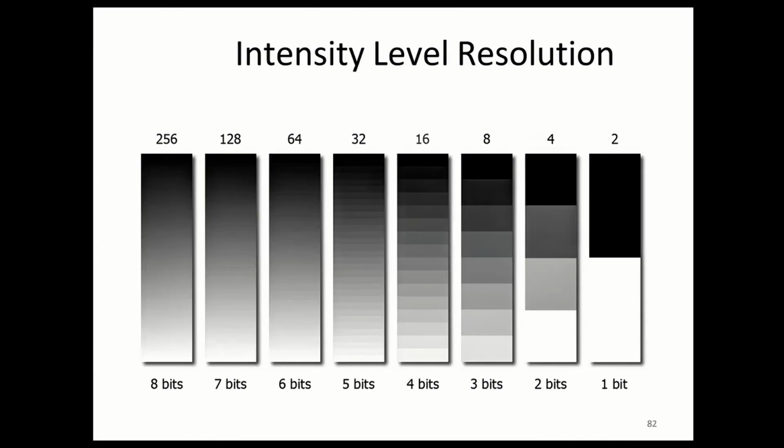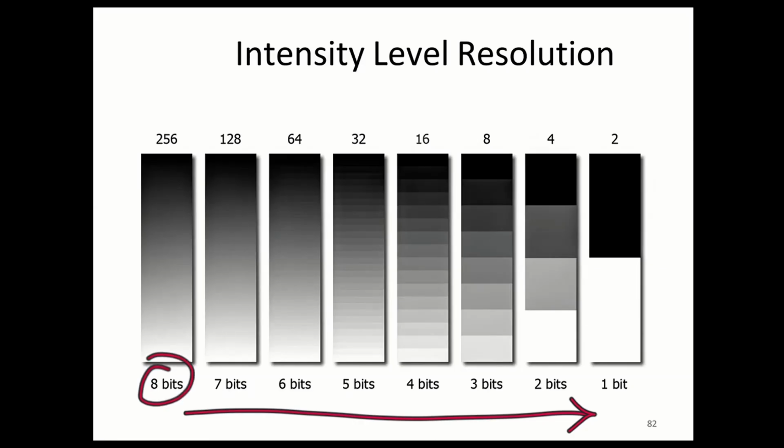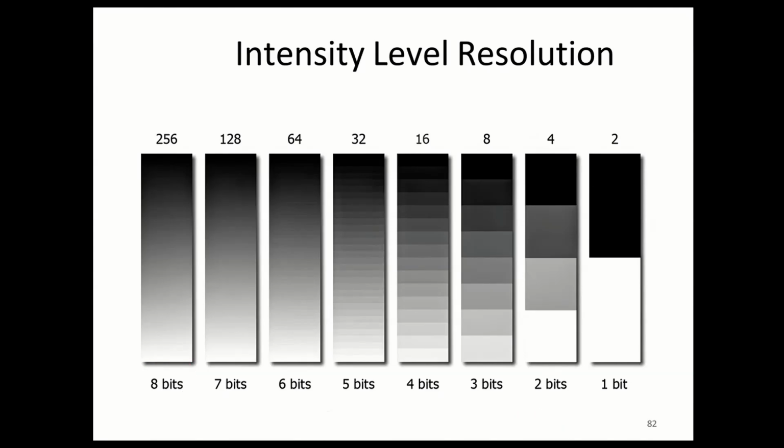Now the quantization. Let's say you have less quantization, what will be the effect? It's a very good example. This is like 8-bit. You can see the shades, but as I move to 7 bits, this is like using 7 levels, 6 levels, and as I go like this, you can see that I am not having that detail that I had there. So now you may have in your mind what quantization can do and what samples can do, and how important they are. The number of samples you decide using the Nyquist theorem.